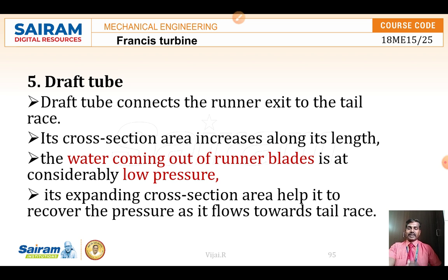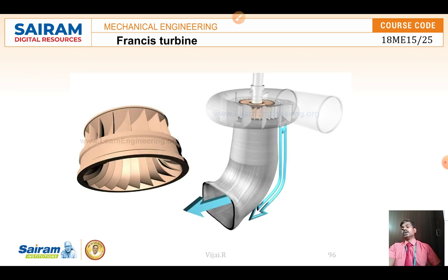So there is the draft tube, which has an increasing cross section, like an extension. When the diameter of the draft tube is enlarged, the cross section increases, so water pressure is maintained and the recovery of pressure is possible. This avoids back pressure, cavitation and all the unwanted damage to the turbine blades.